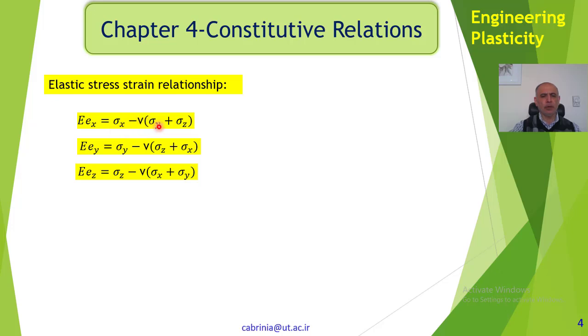That's mu times (sigma y plus sigma z), because if we have the force in the x direction, then we would have strains in the y and z directions, which are given by this Poisson ratio, showing the strains in the other directions. In those directions, the strains are negative, they are compressive. If in this direction it is positive, in these directions they are negative, and vice versa.